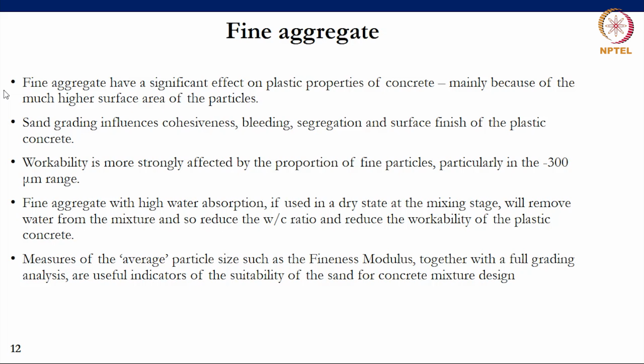Segregation, again, is related to cohesiveness and will influence the way in which particles stay together or separate during compaction. If the aggregate grading is not suitable, during compaction you'll find that a lot of the heavier stone-sized particles will segregate and settle to the bottom. That would be an issue related to aggregate properties, but also to workability.